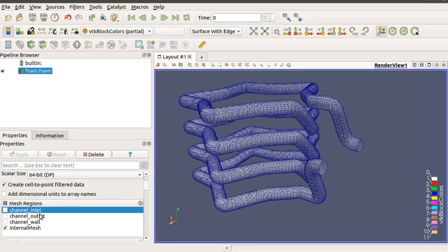So what is the advantage? We can define the input parameters in the 0 folder based on these boundaries. Through the channel inlet the water will enter, and the channel wall will act as the boundary, or it will confine the fluid passing through it, and through the channel outlet the fluid, here it is water, will exit. For that purpose we have created different patches in Blender and exported in .obj format.